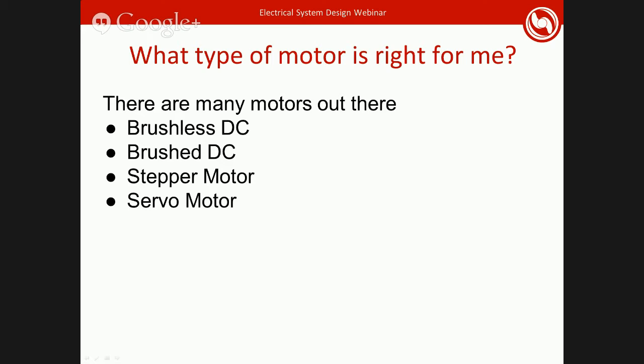In addition, on the other side, you have your servo motor, which basically you give a signal to tell it an absolute position to orient itself to, and it'll hold its position. So looking between those two, we've looked at steppers in the past just because then you get that nice incremental motion. However, both are perfectly reasonable solutions.